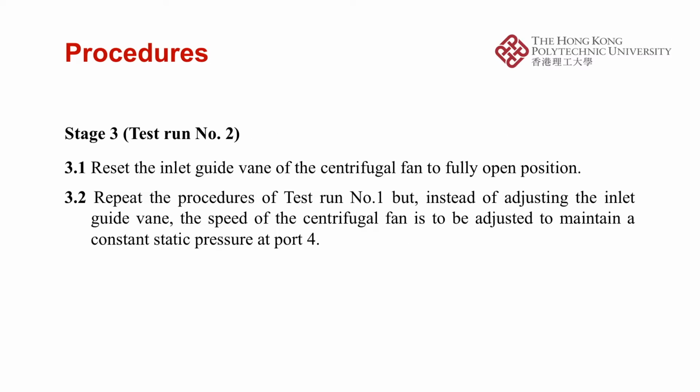In stage 3, reset the inlet guide vane of the centrifugal fan to fully open. Then, repeat the procedures of test number 1, but instead of adjusting the inlet guide vane, the speed of the centrifugal fan is to be adjusted to maintain a constant controlled static pressure at port 4.